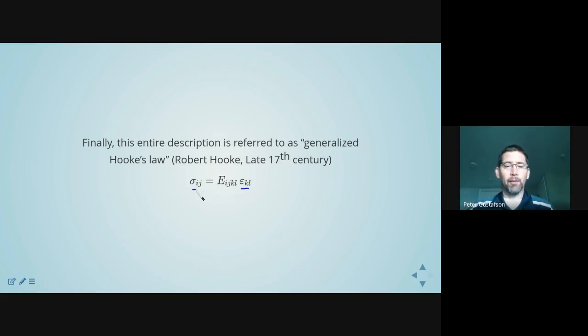You've got a 9-component stress. And in actuality, what you have here is a rank 4 tensor. So it's a 4th rank tensor. This is a 3 to the power 4 coefficient. So really there's 81 coefficients, which we in this class will be representing by that 6 by 6 matrix. But in general, if you did the most general description of that, you could represent it as 81 coefficients, of which 21 could be unique and as few as 2 must be unique.